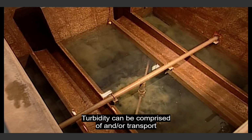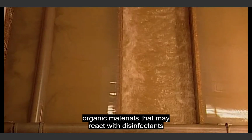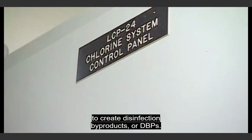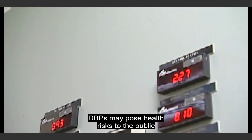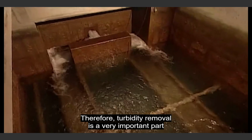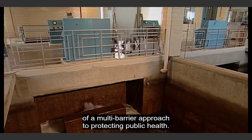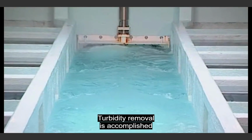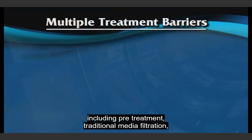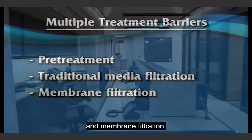Turbidity can be comprised of and/or transport organic materials that may react with disinfectants to create disinfection byproducts, or DBPs. DBPs may pose health risks to the public and must be closely monitored. Therefore, turbidity removal is a very important part of a multi-barrier approach to protecting public health. Turbidity removal is accomplished via a number of treatment strategies, including pre-treatment, traditional media filtration, and membrane filtration.